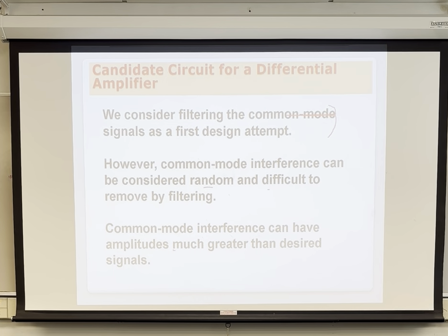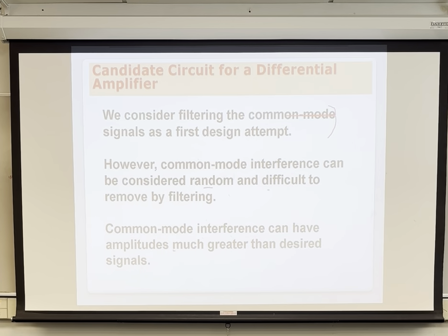It's electromagnetic waves, so it's not visible, but it's basically everywhere, and on everything. And if you go outside, you still have common mode because of all the cellular and communication waveforms that are there. But in here, 60 hertz is a very large common mode signal, an electromagnetic wave. So if you wanted to reject 60 hertz, this circuit has to be capable of rejecting it, even though it's very large, several large voltages. And it can be random.